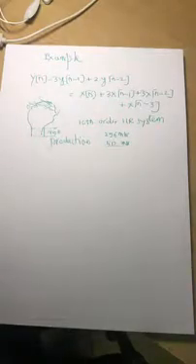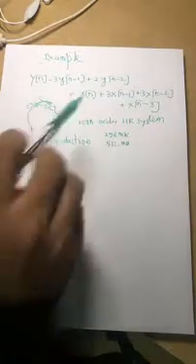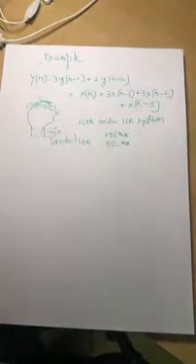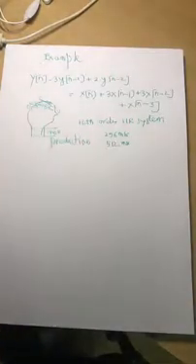In speech compression, you never send the speech, you send actually a difference equation, and the other side takes this difference equation, and usually the input is an impulse, or the input has to do with the pitch of your voice, which is detected. So you reproduce the voice.